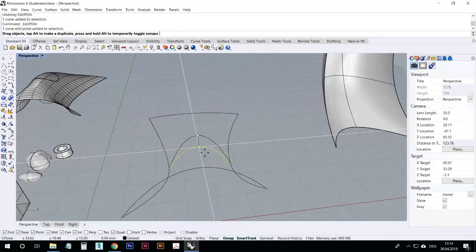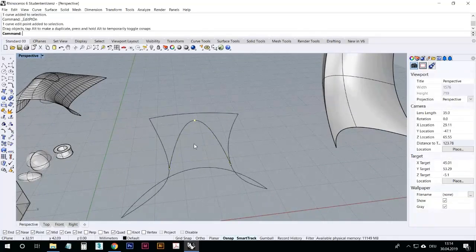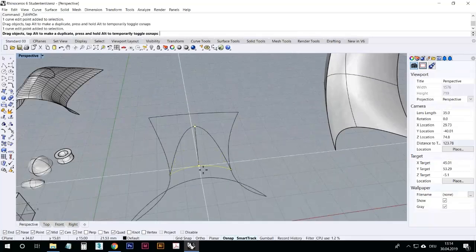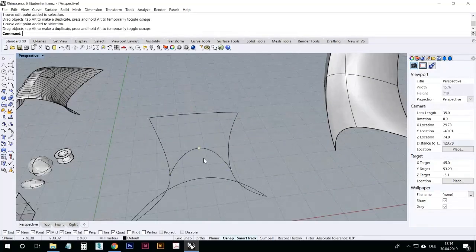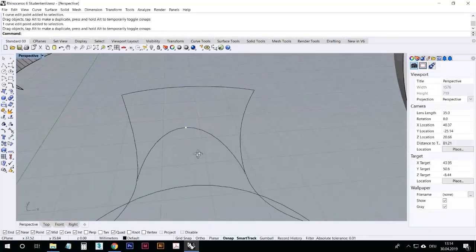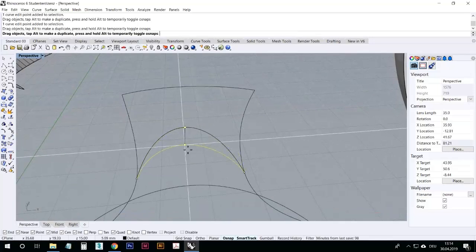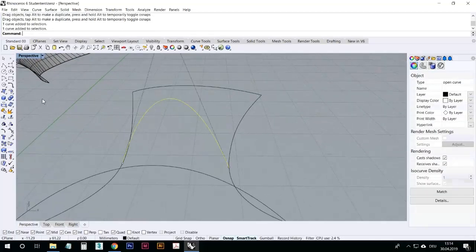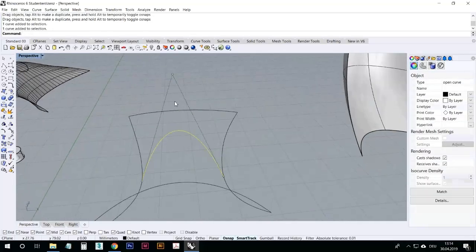In the background now, the other control points are of course also still there. But this means you can pull back and forth with a little bit more exactness perhaps, depending on what kind of curve you have. To exit that, you simply press escape, and that disappears, and then you see that the control points actually look like this if you consider the relation to a 1 degree curve, like a polyline going up here.